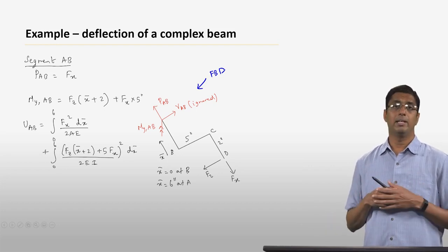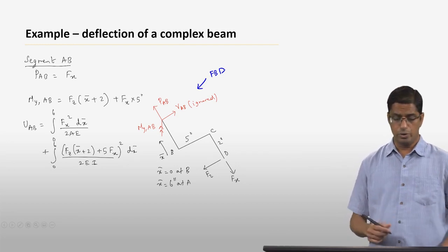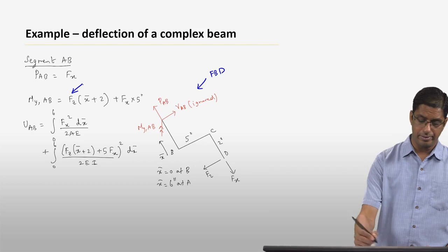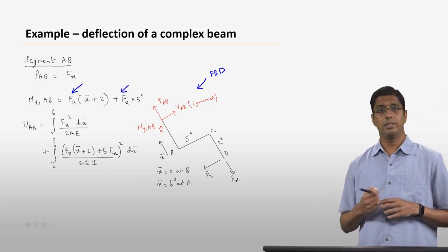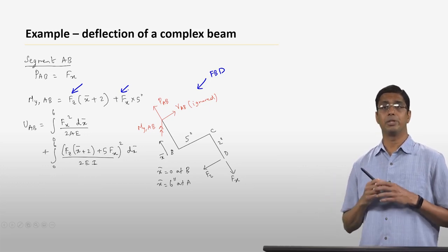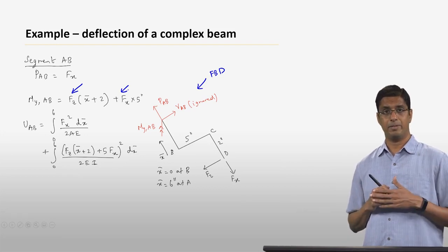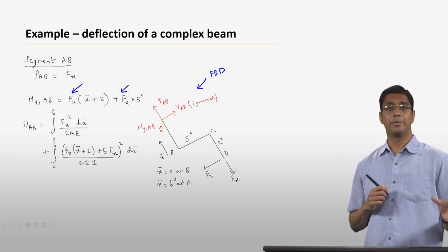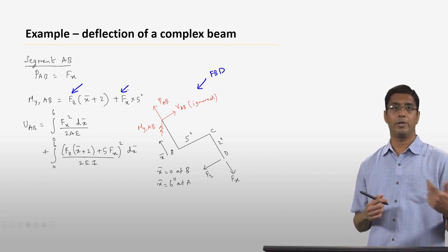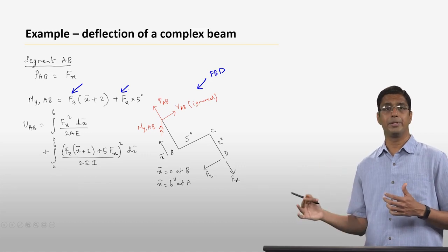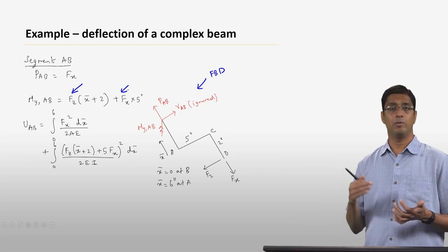The bending moment along the y direction is going to be a little bit more complicated. Okay, so again, there is going to be a contribution due to Fz and Fx. Okay, in this case though, the contribution due to Fx is going to be a constant for any point between B and A. Okay, but the contribution due to Fz is going to be changing. Okay, so this is exactly opposite of what we found in segment BC. There the contribution due to Fx was variable and the contribution due to Fz was constant.